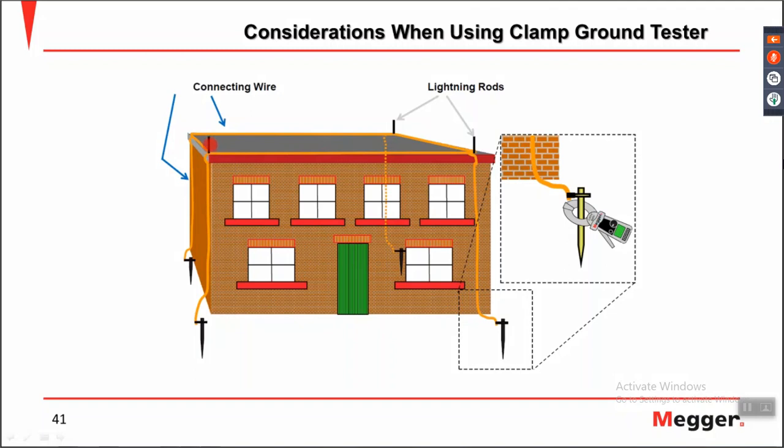You want to measure this ground, but actually this loop is lower than the other loop. So as per Ohm's law, you just measure the resistance value of this bar, not the actual ground resistance value. Yes, you need to make sure the ground electrode is connected directly to the soil.